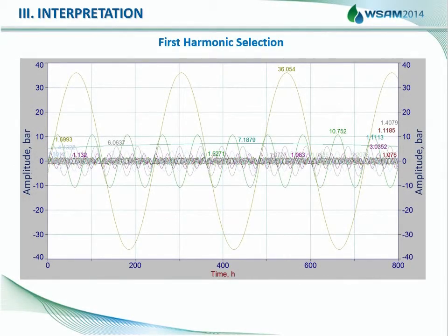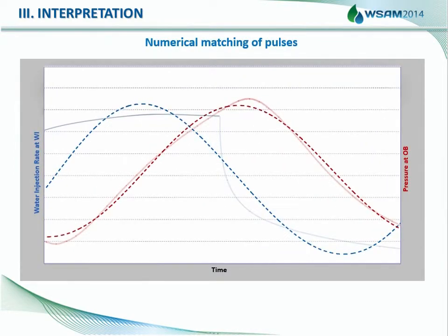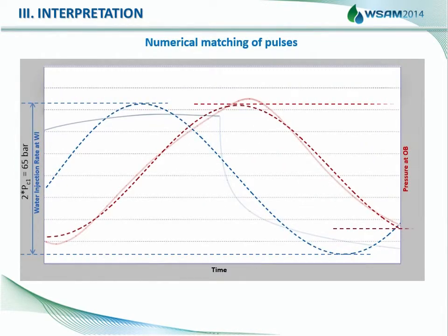The next steps are fast Fourier transform to identify unwanted noises outside the confidence interval, finding the first harmonic of pressure, calculating the pressure amplitude at the generator and receiver wells, and determining the phase shift.